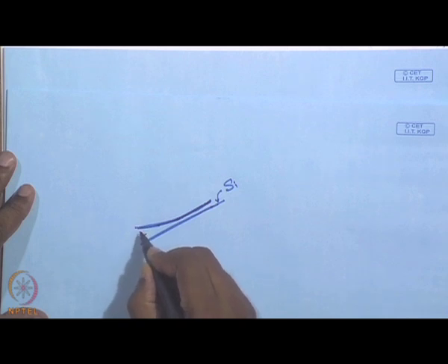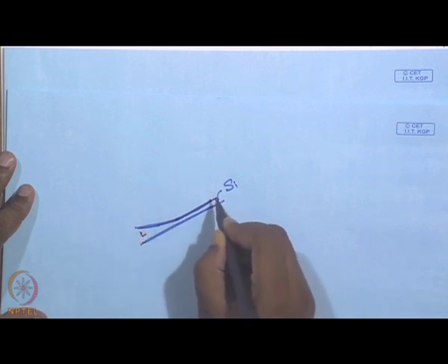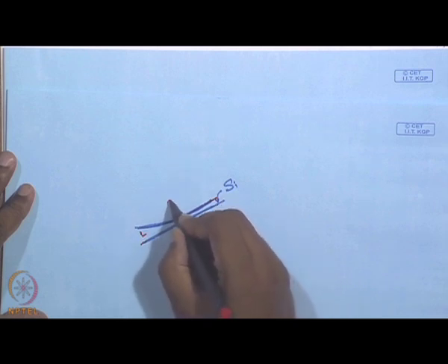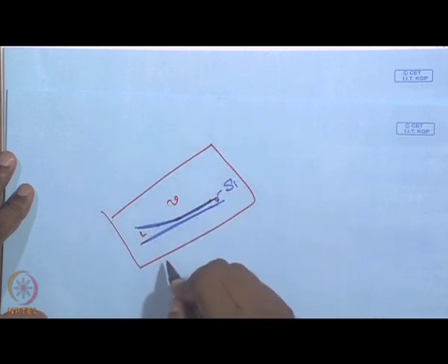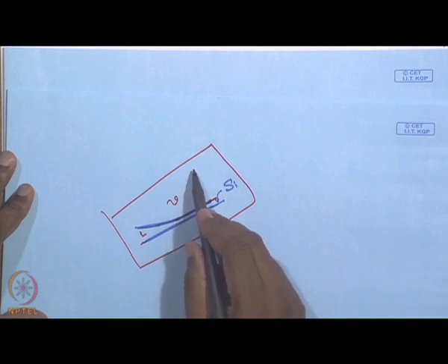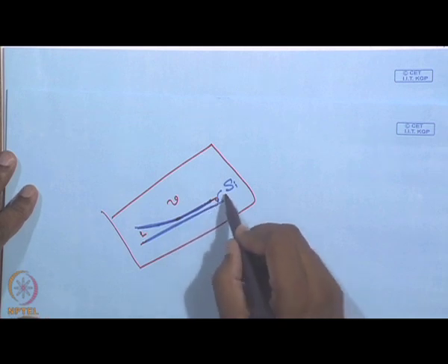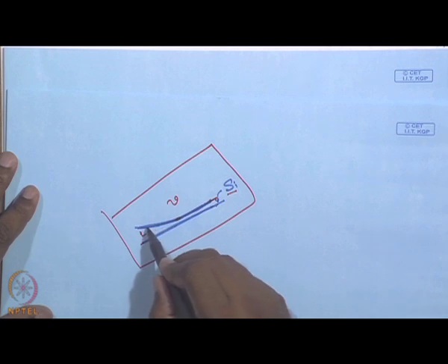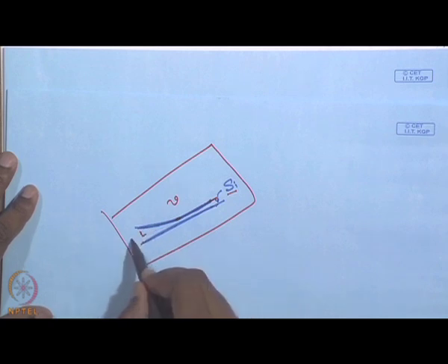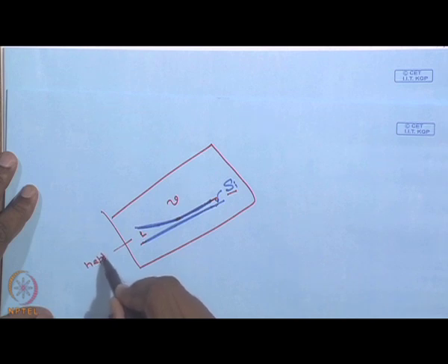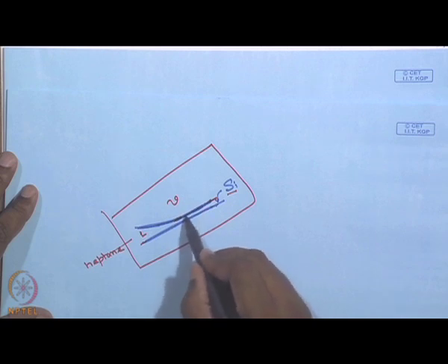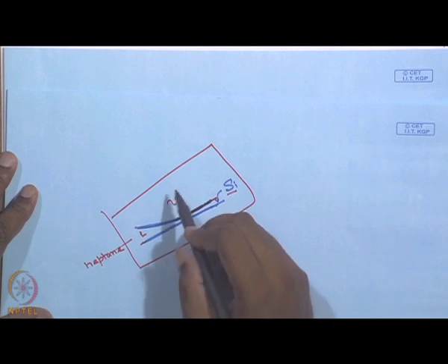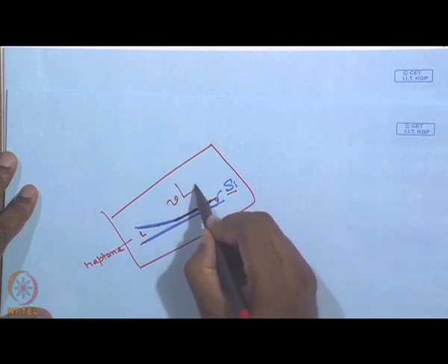So, I have a liquid pool and the film forms on the silicon wafer and this is a vapor. This is enclosed in a chamber such that the impurities from the ambient atmosphere cannot come and adsorb on silicon. So, the silicon is carefully cleaned and then a liquid, and for this specific experiment the liquid used was heptane, ultra pure heptane, and we are looking at the behavior of the liquid film. We are measuring the liquid film using optical methods.